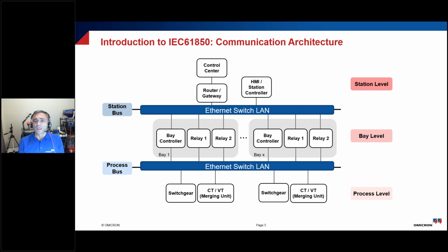If we take a look at this next diagram, it looks quite technical, but you have devices within the substation called protective relays, and they're the devices that are monitoring the power system. Maybe during a storm, you see the lights flash on and off for a very short period of time. It's actually these devices doing those sorts of control operations to maintain and continue the power being supplied in a reliable fashion.